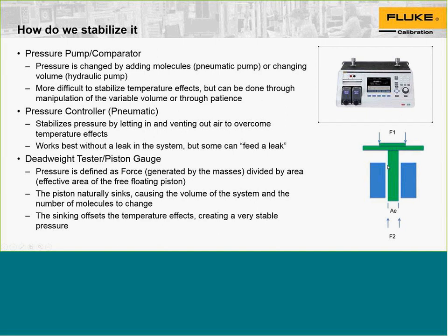Normally, the media is going out of the system in one place. In order to maintain our pressure, we're pushing more media in somewhere else, and we're creating a flow through the system. With a floating piston, you do not have that flow, because the molecules leaving the system are overcome by the volume of the system changing.